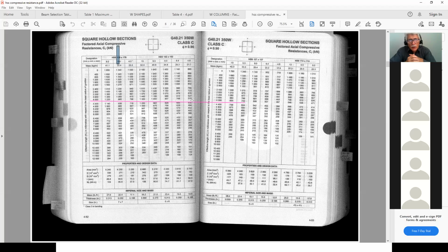If you want to take the lightest one, you make sure you look at, in that range, out of these three possibilities, which is the one that gives me the lightest, and this is where you get the mass per unit length. Okay, so like I said, this one was good here, but it gave me a CR more than what I need. This one was good here, but if I look at how much this weighs, and how much this weighs, and how much this weighs, this gives me an even better CR,